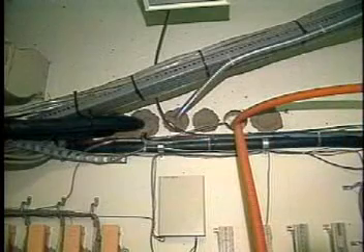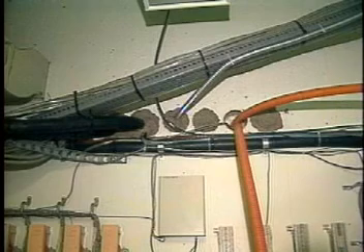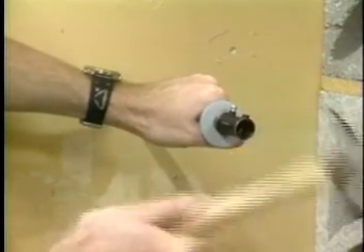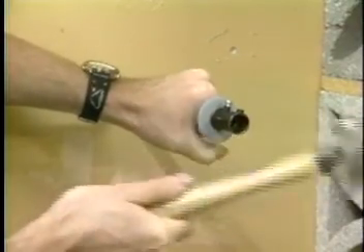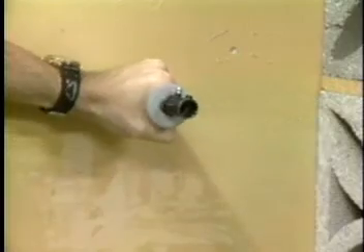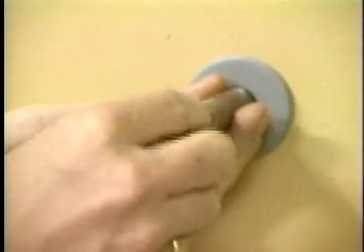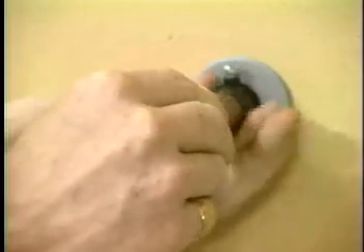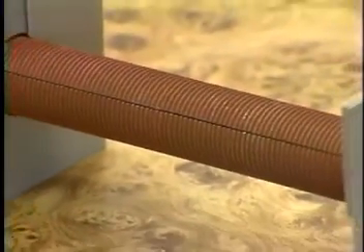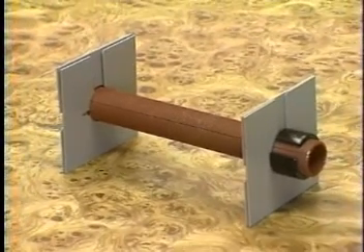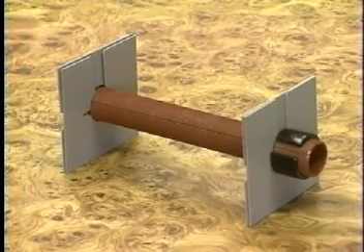When cables must pass through walls, building and safety codes dictate that they must pass through conduit. A quick and efficient way to comply with these codes uses this commercially available sleeve that is pounded through the wall. On each side of the wall, a washer and clamp secures the sleeve in place. A split sleeve is also available that is designed to install around existing cables passing through walls, thus bringing the installations up to code.